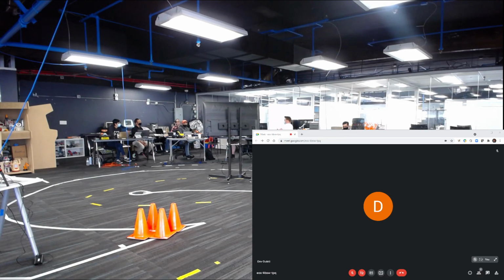No, because there won't be any real sensor data coming. You can run it, but it won't go anywhere. In the perception demo, there's a ROS bag, and you can play back the ROS bag and do the rest of the perception. That'll at least get you a stack running with some real data.